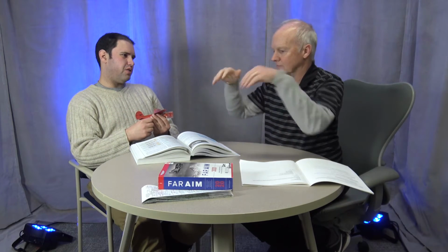Plus, when you're going slower, your control surfaces need more deflection to be effective too, correct? Right, correct. And then you can also have devices on the leading edge of the wing, flaps or slots that open up to increase airflow over the leading edge of the wing to delay the stall as well. Jet airliners almost always have those.